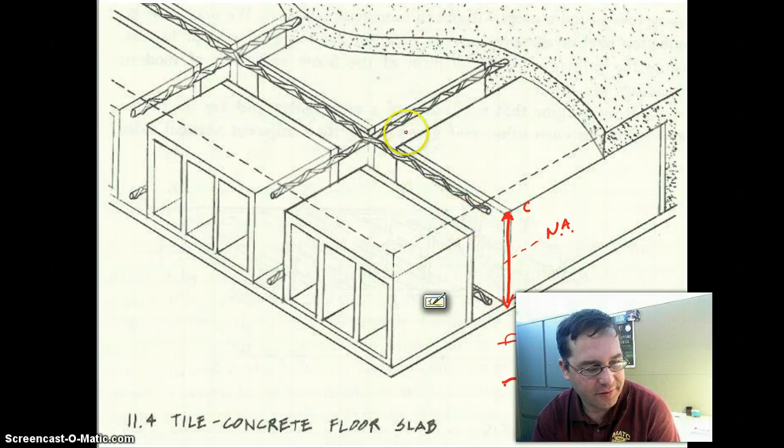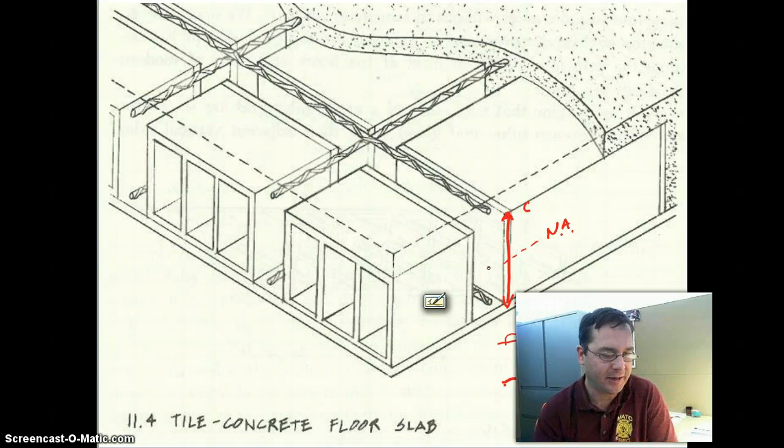So you can see that it depends on where the supports are and where the floor is loaded, whether the tension is in the top of the floor or in the bottom of the floor. To be ready for all possible scenarios, the floor is constructed with reinforcing bar, both top and bottom. And this is really pretty economical to just put rebar on both sides of it. What you end up with is a very, very robust floor structure.